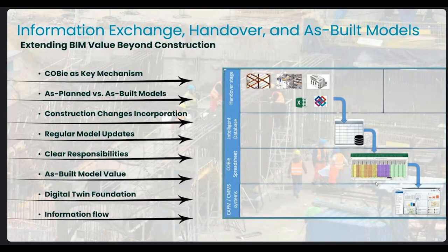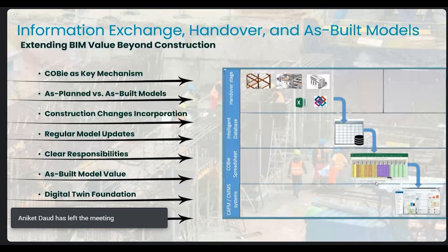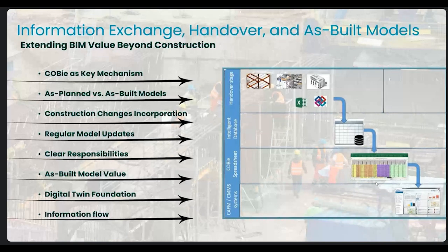So regular model updates. As I told you, if you are performing something with respect to the as-built changes, whatever things you are installing on site or additionally adding on site, it may be ladders or it may be small devices also, those also need to be updated inside the model to track and to get the real time data. Okay. So it has clear responsibilities with respect to the job roles and designations that we have designed for each and every participant. They need to be followed.